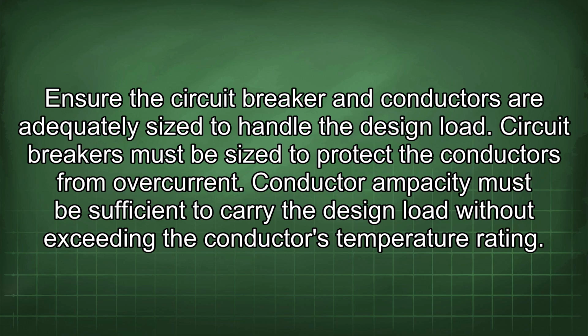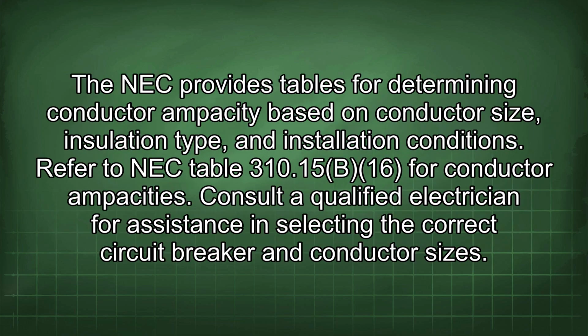Ensure the circuit breaker and conductors are adequately sized to handle the design load. Circuit breakers must be sized to protect the conductors from overcurrent. Conductor ampacity must be sufficient to carry the design load without exceeding the conductor's temperature rating. The NEC provides tables for determining conductor ampacity based on conductor size, insulation type, and installation conditions. Refer to NEC Table 310.15(B)(16) for conductor ampacities. Consult a qualified electrician for assistance in selecting the correct circuit breaker and conductor sizes.